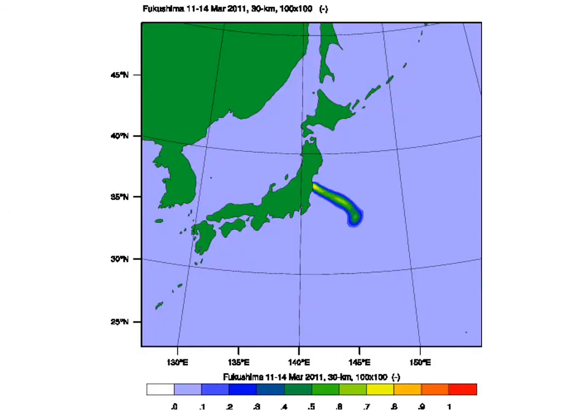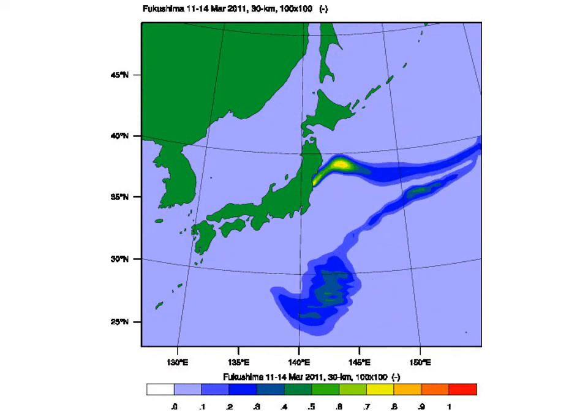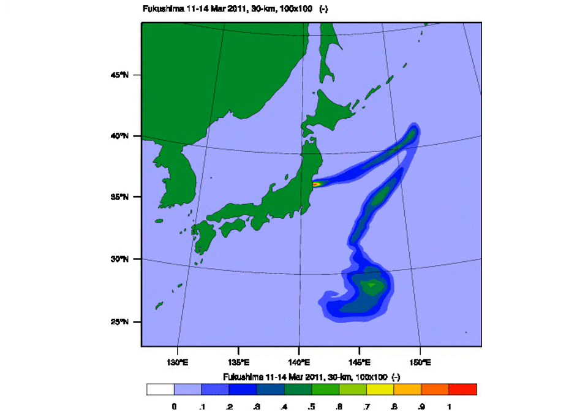The end result is an hourly output of a non-dimensional plume variable that's being emitted from the Fukushima site. So again, it's important, only a couple lines of changes in the registry and 1 do loop in the solver are required.